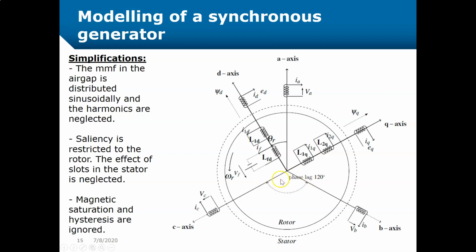And then we have two other axes that I just mentioned earlier: a D axis and a Q axis. They are locked to the rotor, as you can see here. The Q axis is 90 degrees behind the D axis in this figure. You can also see an angle here, theta. Here it's theta R, but in the book theta D is used, and it indicates the position of the field winding and the D axis relative to the A phase.